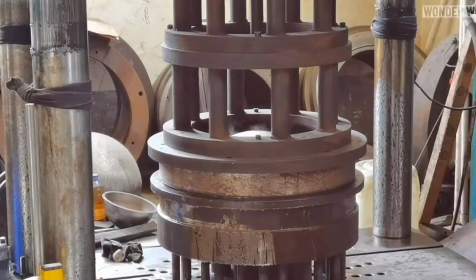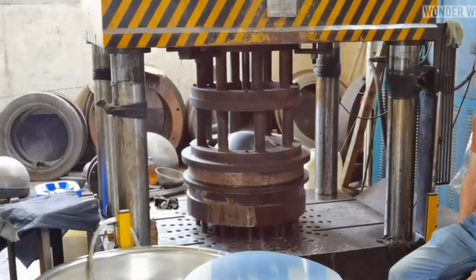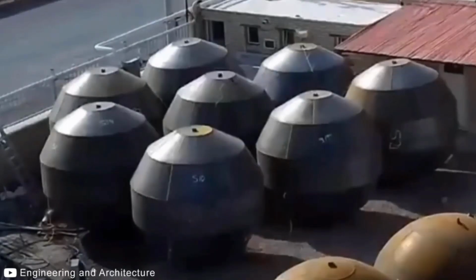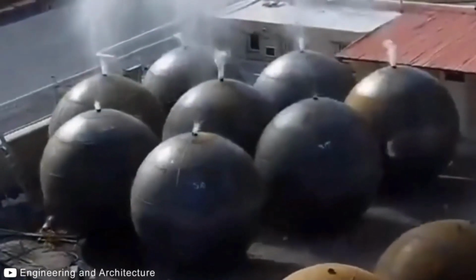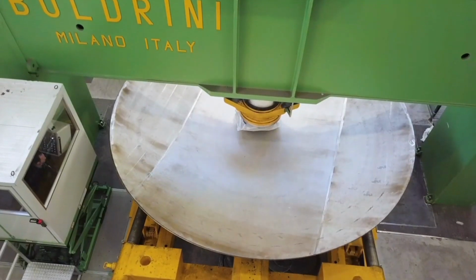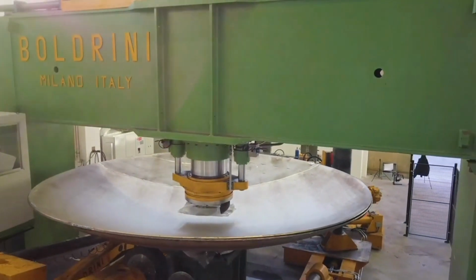Then stamping or deep drawing involves pressing a sheet metal blank into a spherical shape using a series of dies or punches. This method would be commonly used for smaller to medium-sized spheres and is suitable for mass production. Finally, there is also hydroforming, which involves using hydraulic pressure to shape a sheet metal object. It can be some sections of cones welded together, either by using a die or mold with the desired spherical shape or not. This would be fine for thin, complete spheres. In the first two cases, you would always have some excess materials or size allowance to later remove it by machining.